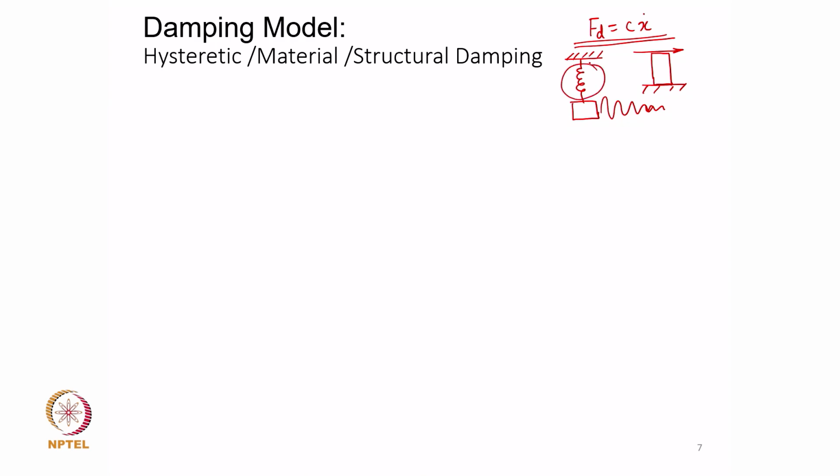predominantly the intermolecular friction, or structural dissipating forces set up inside the spring as it stretches and undergoes mechanical strain. That is actually responsible for converting the energy of vibration to heat because of internal damping, right. So, that structural damping is the damping responsible for dissipation of vibration energy when there is no formal dashpot attached, notwithstanding any other kind of damping. For example, if this connection point has some relative motion, then there will be some frictional damping also coming into the picture, plus the mass, if it is moving with higher velocity, will have aerodynamic damping.